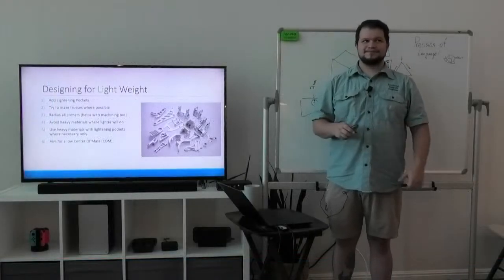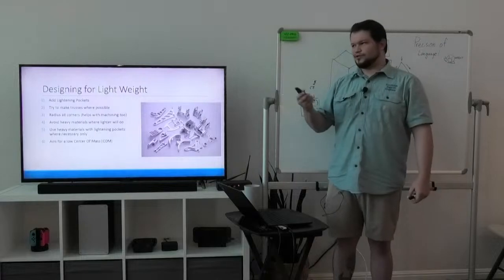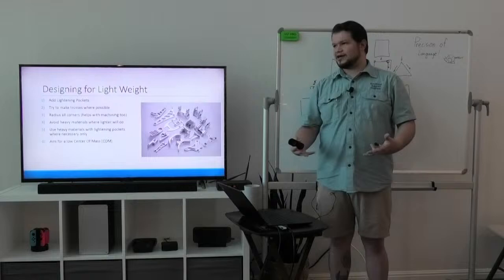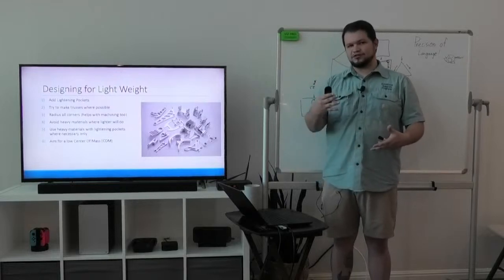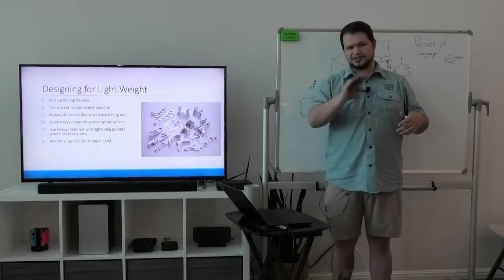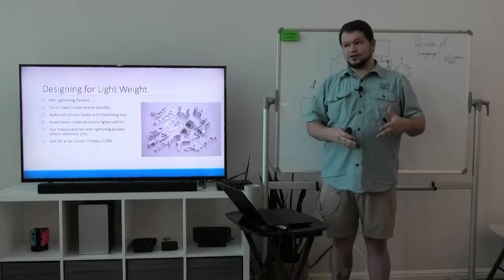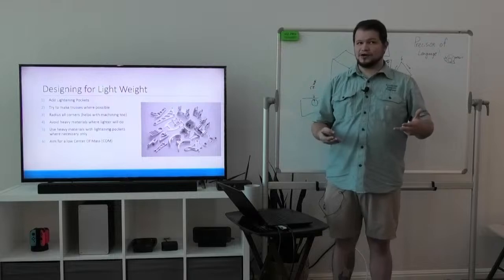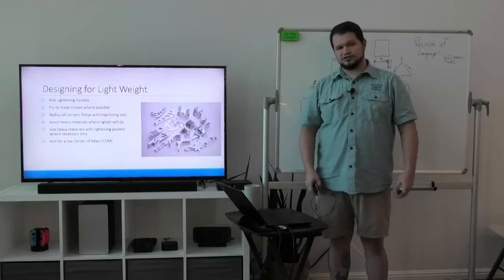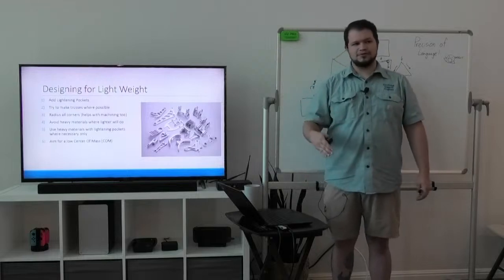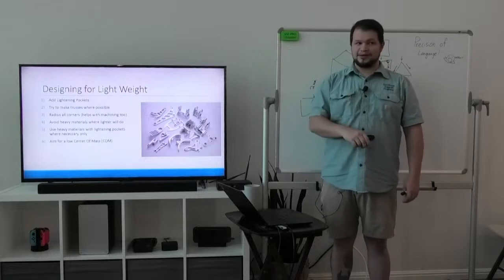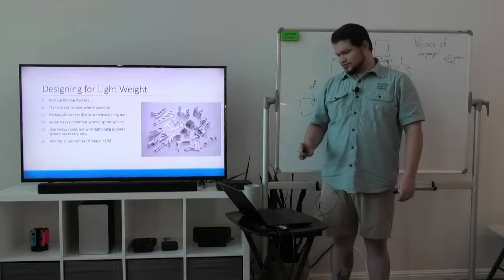Not necessarily. The answer I'm looking for is when you have a low center of mass, it keeps your wheels engaged when you have a light bot. If you have a higher center of mass, it's easy for those wheels and the friction to make your bot pop wheelies, even if your overall weight isn't that bad. If you can have a lower center of mass, it'll keep your wheels on the ground, which will give you more speed. So you have to worry about how much weight it is when you're going lightweight to keep your motors engaged on the ground.